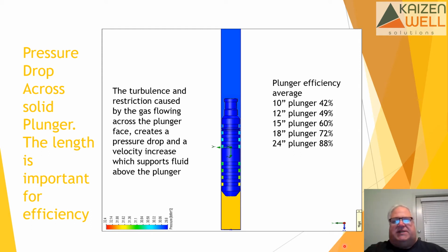We used basically two 24-inch plungers on either side of a big long spacer bar. Those plungers were so efficient with those two 24-inch seals that when we tried to drop them, you couldn't get them to fall. It would get into the tubing, and it barely moved going down.